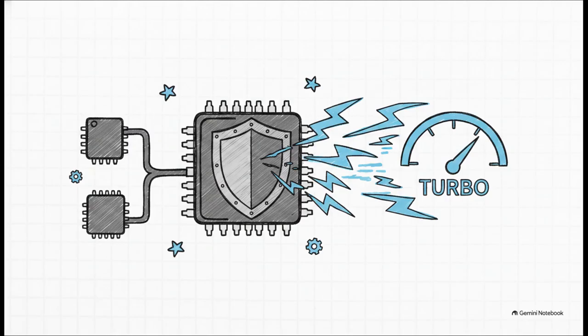It doesn't just check the box for the modern ISO 11898-2:2016 standards. It really pushes the physical limits of the bus. Obviously, it easily handles classic CAN and your standard 2 megabits per second CAN FD. But if you grab the G suffix option, you can push your data rates all the way up to a blistering 5 megabits per second. Plus, it plays perfectly with both 3.3-volt and 5-volt microcontrollers. Oh, and those H variants? They can withstand up to plus or minus 70 volts of bus fault protection. I mean, that is some serious electrical armor for high-speed data.